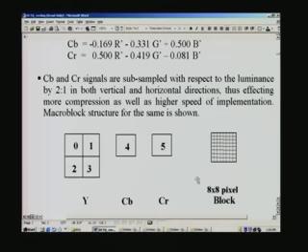Now, what we have seen is a picture, the entire picture that you saw right at the beginning, the parrot namely, is actually 1024 by 768 true color. That means you need 3 bytes for representing a color of YCbCr, or even if it is gamma corrected RGB in the raw format, you need 1 byte for each of the color components.